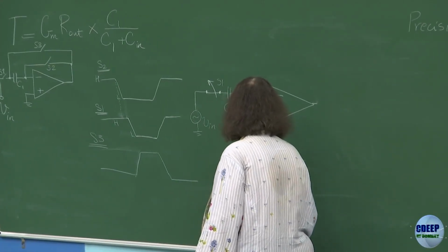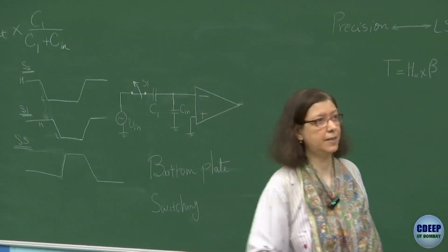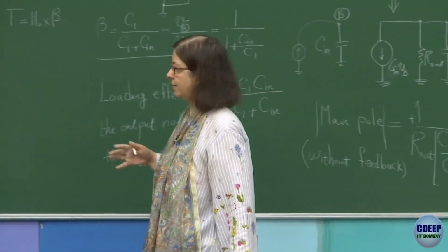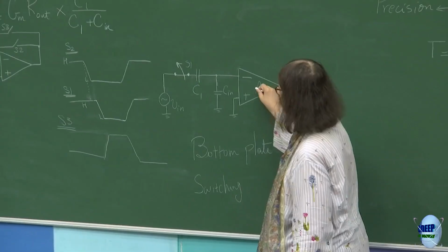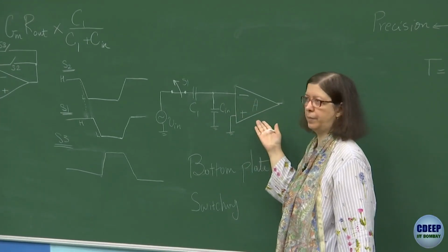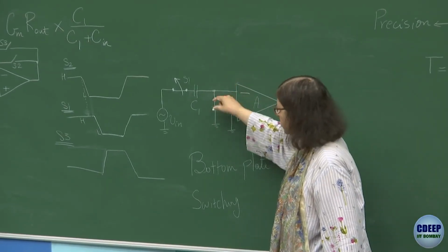If you have a high impedance node, in fact, it was in the CDAC in the SAR ADC, and based on that I eventually made a generic case. This is also similar to that case. The only difference is that instead of a comparator, we have an op-amp. Doesn't matter. All that happens is that from a DC point of view, this node is floating.